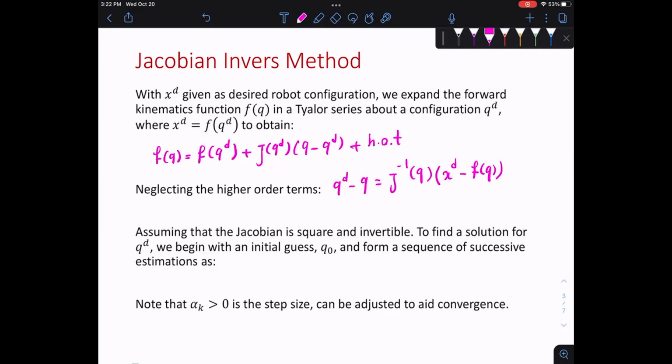The diagonal. So you can define some weight. So this joint has more effect on the position of my end effector, so I'm going to give it a number that will have more effect. And then once you recalculate, the new iteration is calculated based on the importance of your first joint. That is also one way of defining step. Or you can say, no, for time 0 to 10, go 0.1 step, and I'm going to solve and see if I converge or not.